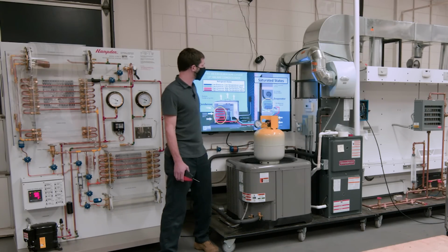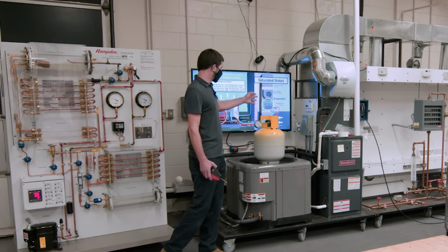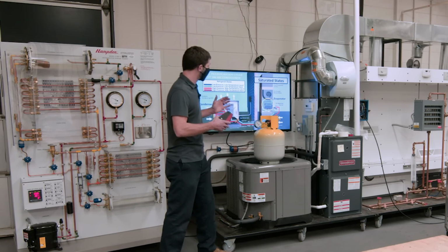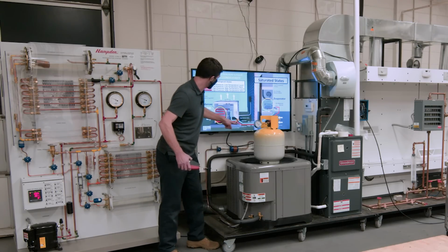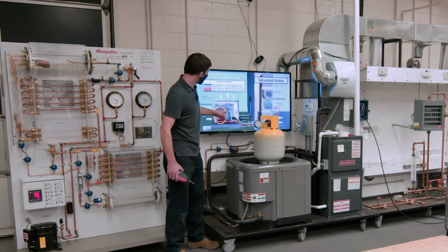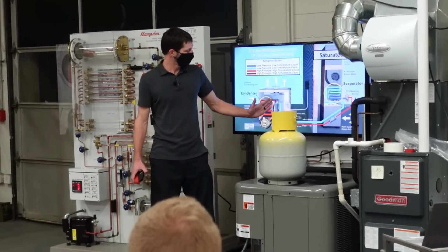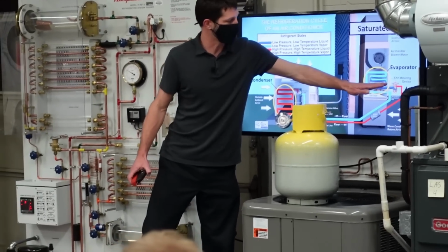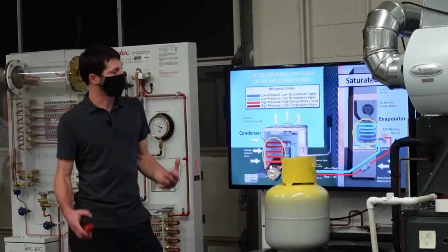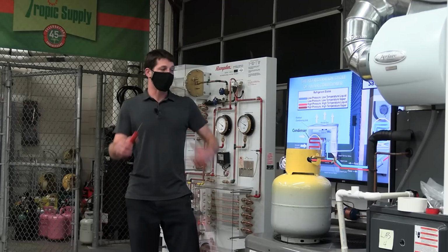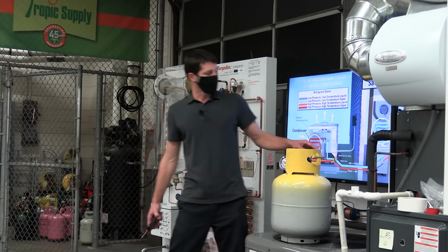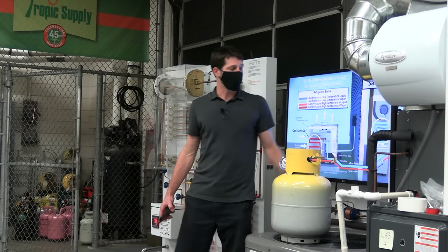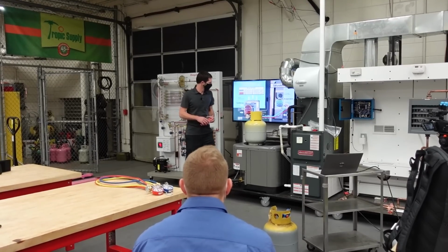It's going to trap the subcooled liquid there, so that when it starts back up again, it already has liquid fully in this line right here. And so basically you have the compressor locked and shut right there when it's off. And so there's always going to be a pressure stop basically right there. So from here to here, it's going to trap and not allow equalization of the pressure across the thermostatic expansion valve for a hard shut-off TXV. And that's just for the next time when it turns back on again, it wants to get the subcooled liquid into the thermostatic expansion valve immediately instead of waiting over time.